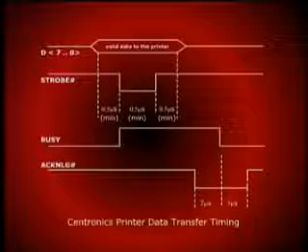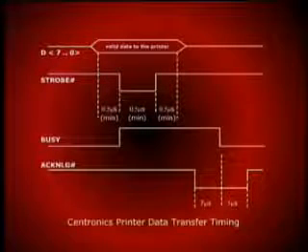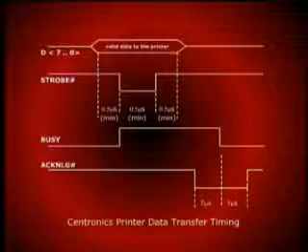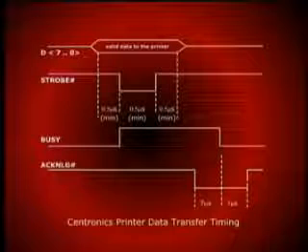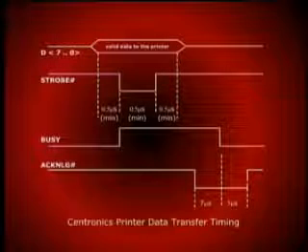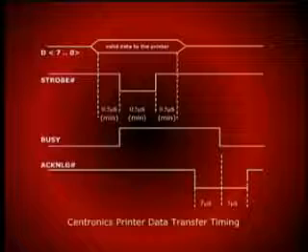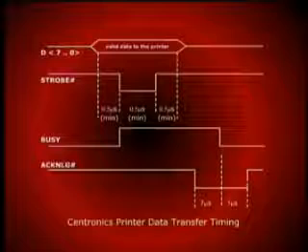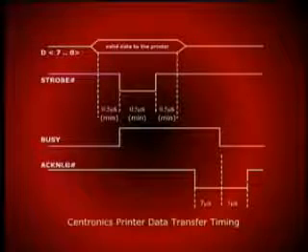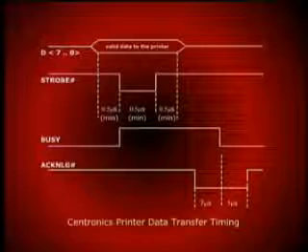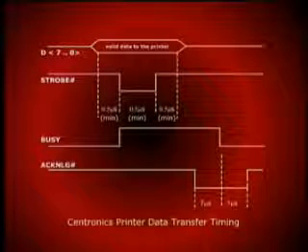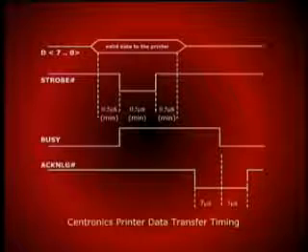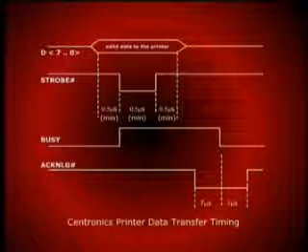When the printer is ready for printing, the CPU starts data transfer to the printer by placing the 8-bit data, which in our example corresponds to the ASCII value of the character to be printed, onto the printer data bus. After this, a negative pulse of duration at least 0.5 microseconds is applied to the strobe signal. Input pin 1 indicates this particular signal, which is strobe low. It is low active.